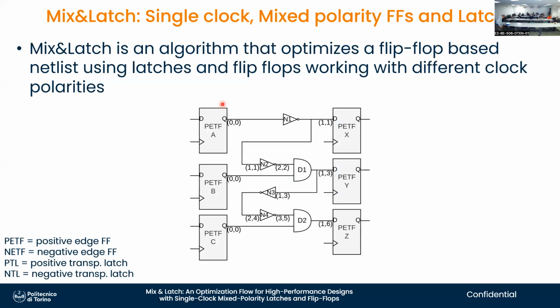Here's where we come in. So what we are trying to do is start from a flip-flop based design created at the register transfer level by a designer, and then convert it into the most efficient, the most high-performance implementation we can. And we go through several phases. We start from a design with positive edge-triggered flip-flops everywhere, because this is the standard methodology. This is what every good digital designer knows how to implement, with combinational logic in between.